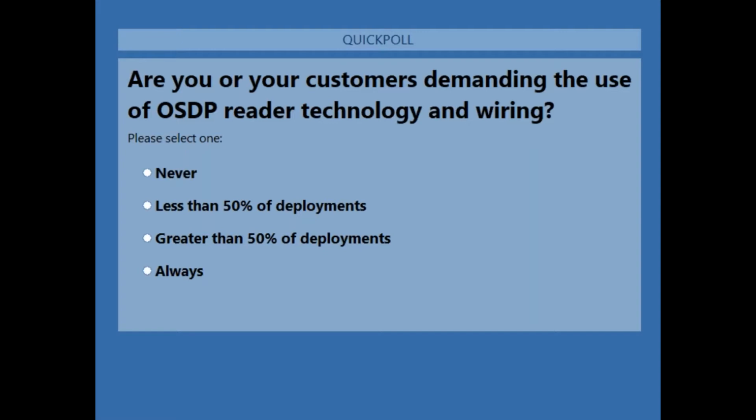So here's, again, I'm going to beat this horse to death today. Mercury MR62, once again, if you want to put 4 readers in there, sure you can. It's good for 2 doors, 4 readers, in and out readers. Okay, and please provide power locally.